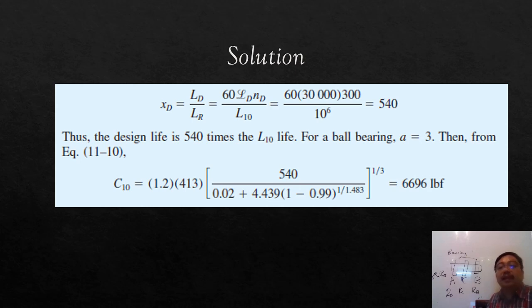And then the bearing life is 540 times the life, meaning that you can expect the life rating to be longer, and then you can predict when you want to do maintenance. Let's say 540 times the life, you calculate the life in hours, maybe equivalent to 1 year. After 1 year, you will tell your worker or yourself to do maintenance, to change the bearing after 1 year of usage. This is what is meant by 540 times the life.